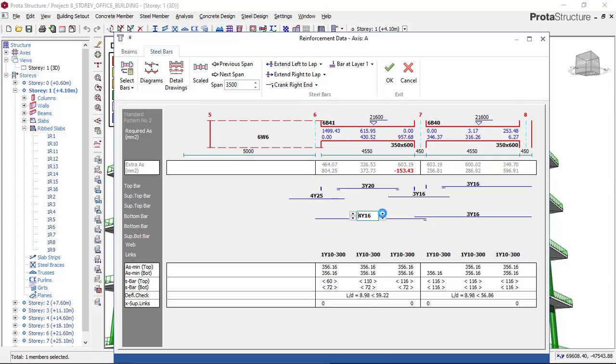So you can see how we're taking our time to check the size of reinforcement, which is okay. So you check all this. Let me reduce this. I don't want 25. Let me check that to be okay. And let me increase this to add a layer for this, because 25 size of reinforcement is way too costly for most clients to afford. As you know, we don't just design our building to stand. We also consider economy, to save money for the clients. So this is now okay.